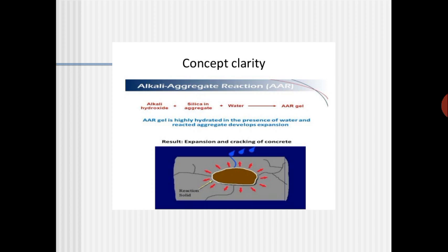Even in contraction, if the percentage of silica decreases, cracks are going to happen due to the decrease in the silica. And make sure that when this alkali aggregate reaction happens, normally expansion happens. When contraction happens, you can see the cracks that are found in the concretes.